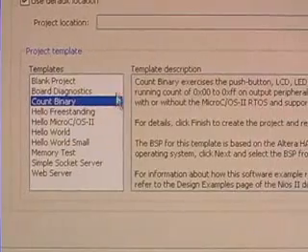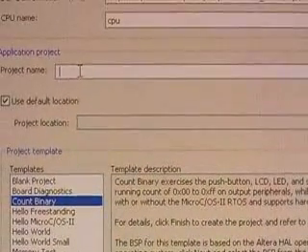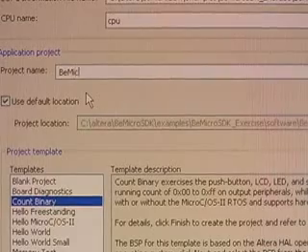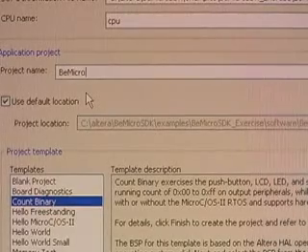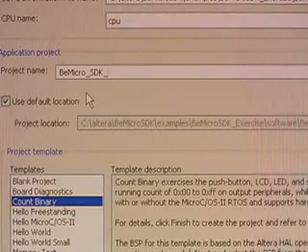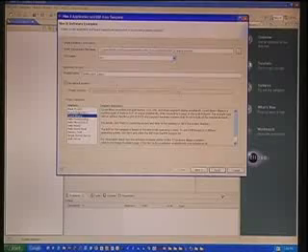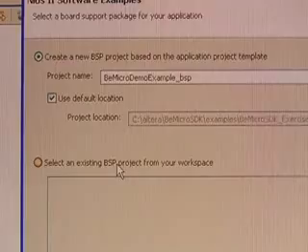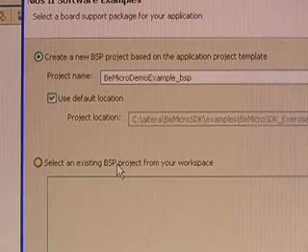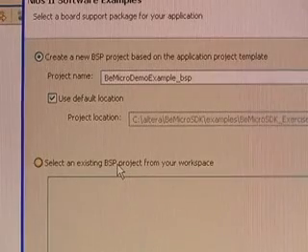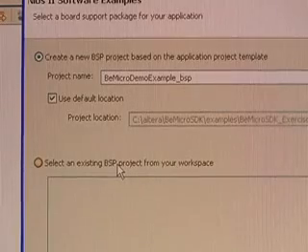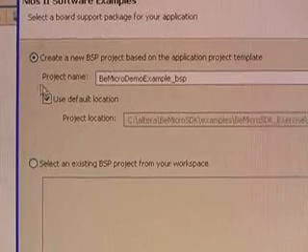And then I just need to give our project a name. So I'll type here B-Micro SDK. And then push next. And you can see the option here to create a custom BSP based on the SOPC info file that we've selected. This file describes the entire processor system, including all the peripherals, the memory map, and so on. We definitely want to do this, so we'll leave this option selected and then push the Finish button.